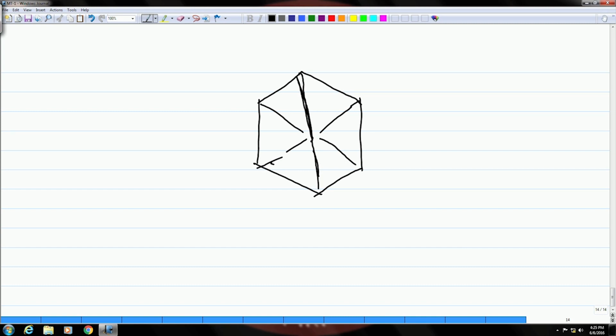And you may also see that along a particular slot, more number of particles are being attracted compared to other slots which are in other directions, this direction or this direction. Okay. And if you remember, I had said that best visibility of a discontinuity is when it is perpendicular to the direction of the magnetic field. Okay.